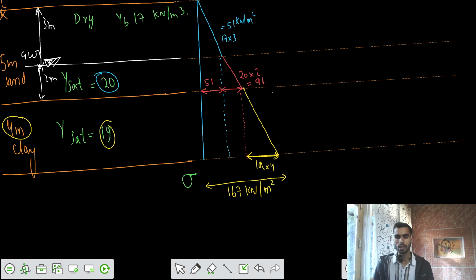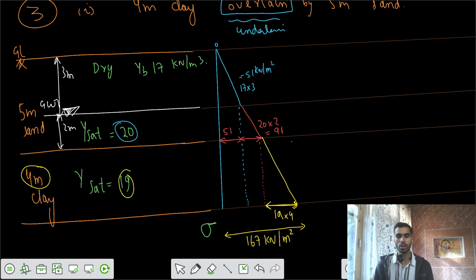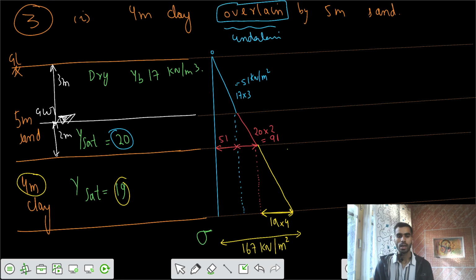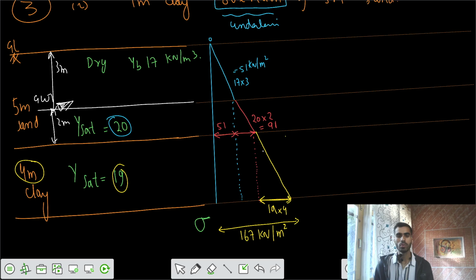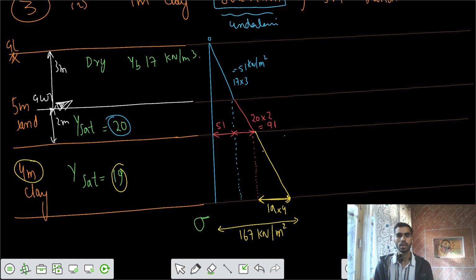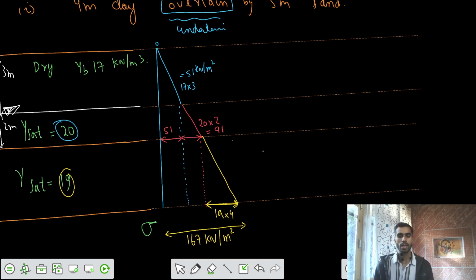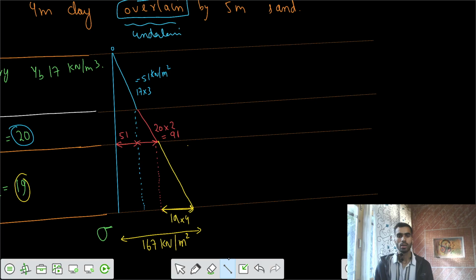Okay, is that easy? It's a linear function of the depth. We just multiply the length, see what the elevation difference is between the 2 points, and join them by a straight line. It's easy. After that, let's go for the pore water pressure distribution diagram.